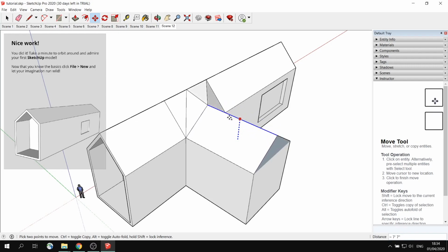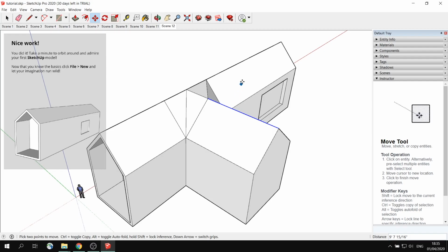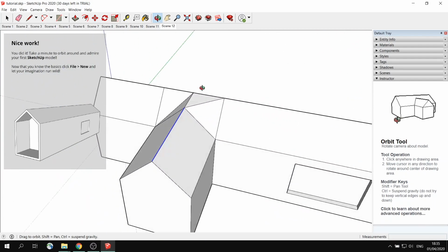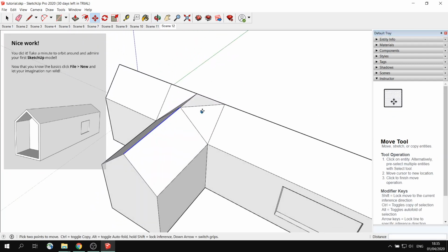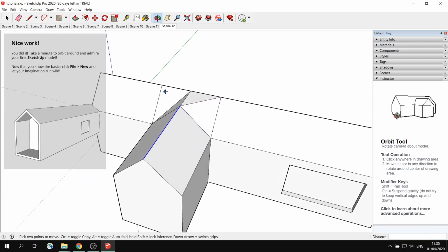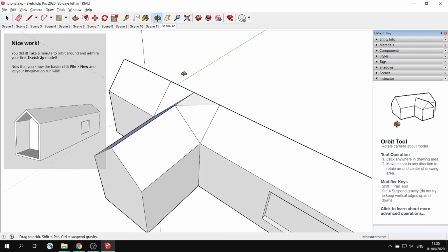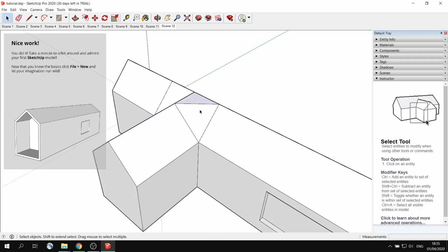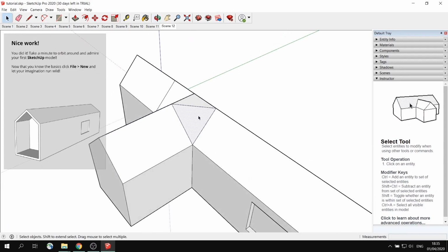Okay, and you can see you can decide the height here. You can also, if you move your cursor and align it to the ridge, you can align it to the same height as the other objects. So for example, the rooftop in this case. Okay, so if I do that, it will create pretty nice geometry. So it's a little bit wrong here, we can fix it. But on this side it looks correct. So let's just fix this part. So I will use select tool, and I will select the parts that I don't want. So I will select this, and I'll press delete, and I'll select this, I'll press delete, and I'll select that line in between, and I'll remove that too.